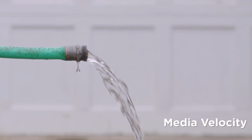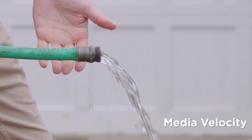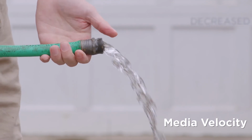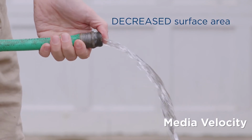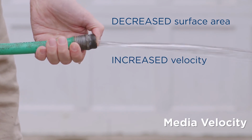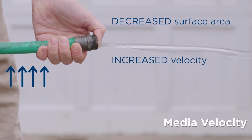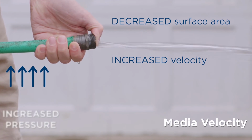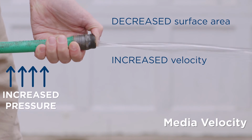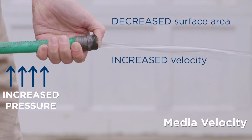If you think about it, take a garden hose with water trickling out of the end. Put your thumb over the end of the hose. Now what you just did is you decreased the surface area that water can go through, and you increased the velocity of the water coming out. But if you look at the back side of the hose with the water coming to your thumb, you just increased the pressure on the back side of that hose. That is exactly what happens when you put a 1-inch or a high restrictive filter on an air handler.